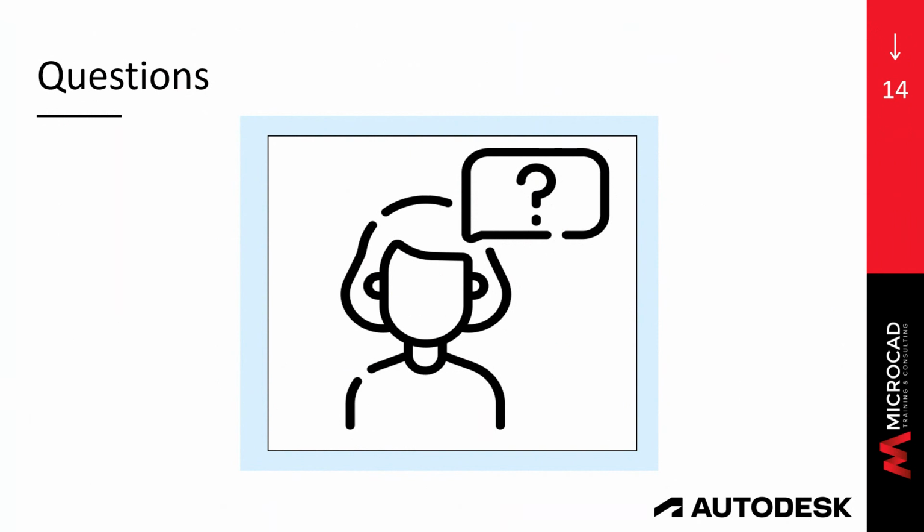Perfect, thank you. The second question we have is, how is this different from other types of generative design? Well, generative design in Revit basically enables users to interact with generative workflows directly in the Revit context. As you can see, you can select Revit elements, define goals, run a study, and then create elements back in Revit. I didn't show you that part, but you can create the elements back in Revit once you have made your design decision.